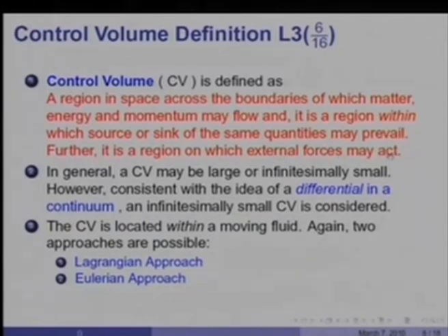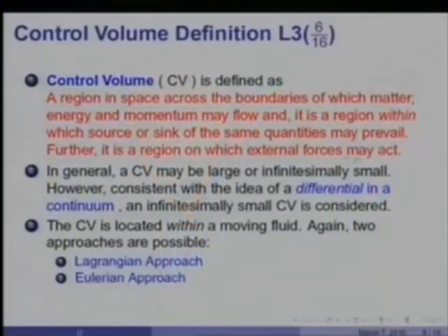So, imagine a very tiny fluid element inside a fluid flow. Then we are saying that in this fluid element, energy will flow in and flow out, mass will flow in and flow out, momentum will flow in and flow out, and it is an element on which external forces may act. In general, a CV can be large or infinitesimally small. However, consistent with the idea of a differential in a continuum, an infinitesimally small CV is considered.